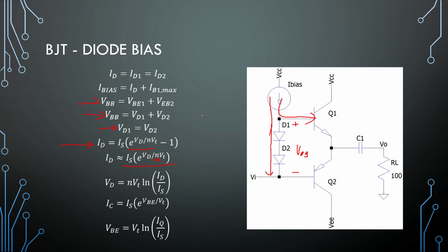If you forget that, these problems can mess you around for quite some time. This N in books is typically assumed to be 1. The value is in general between 1 and 2. You will find this in the SPICE model of your diode.